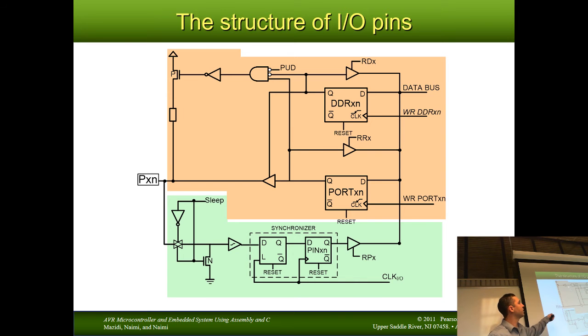So the only 2 things you really need to worry about are the DDR needs to be 0 and the port pin needs to be 1. But because the DDR is 0, that 1 on this port register doesn't make its way to the physical pin. The rest of this is the input section.